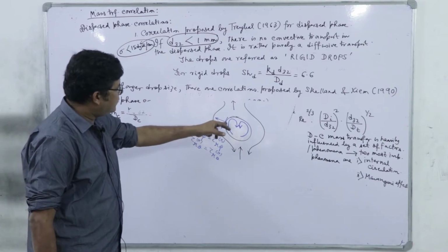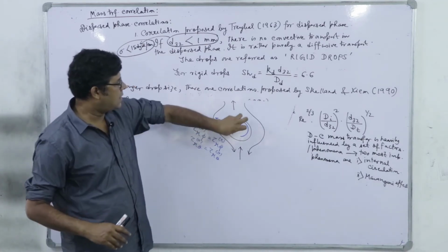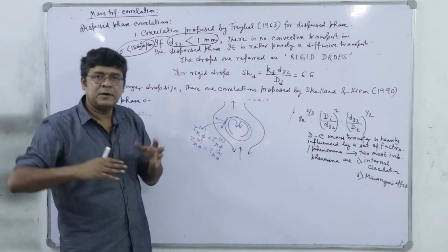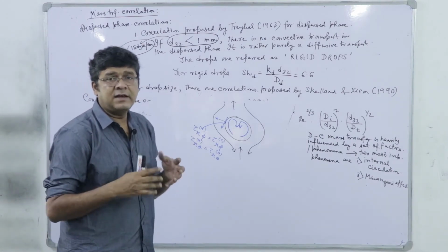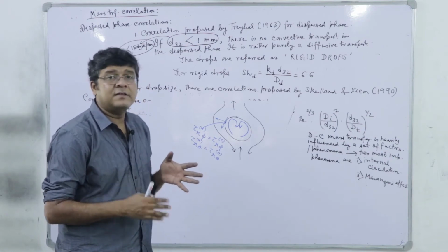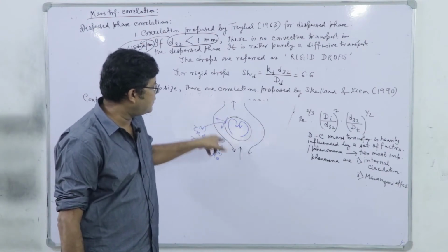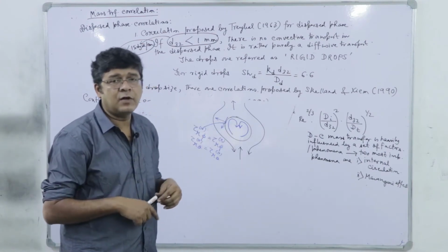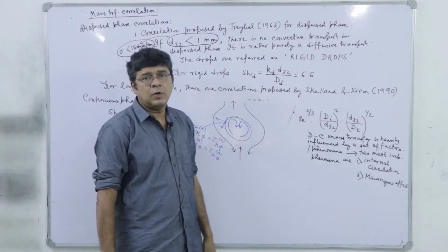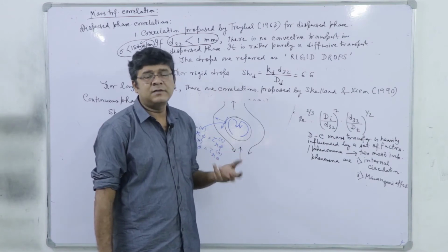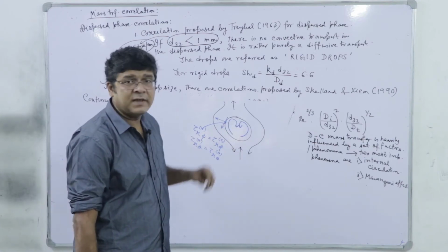As a consequence, since the shear stresses on the dispersed and continuous phases are the same, the fluid inside the dispersed phase is also subjected to that shear, and it will evidently be set in motion if the drop size is above 1 millimeter. There will be a convective current inside the drop, and the dispersed phase mass transfer coefficient is heavily increased. So internal circulation is a phenomenon which heavily influences the dispersed phase mass transfer.